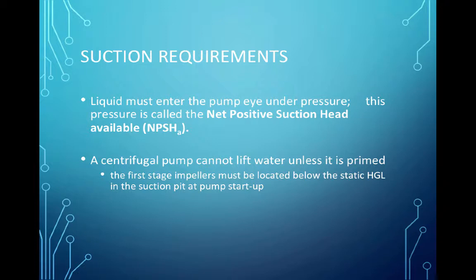So in the case where maybe there is that much of a lift, the suction tube has to have an alternate entry point. When you're priming the pump, you literally take a secondary supply of water that's big enough to fill that tube maybe 1 or 2 times over. You put water in the tube as rapidly as feasible at the same time you start the pump, and that will often prime it. Now, if you don't turn the pump on, air will still leak back in the system. The water that you fill on the suction side tube will drain out, and it does it pretty fast. So priming a pump is not something you can do willy-nilly.